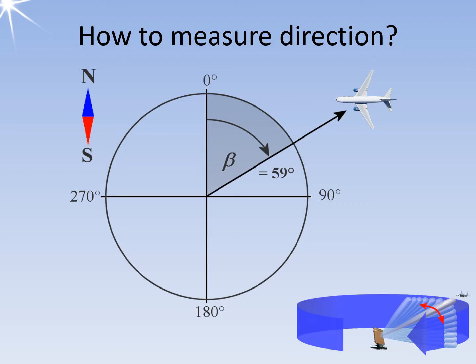Three-dimensional measuring radar sets divide the antenna pattern into narrow sections and measure the distance individually within these sections. Thus, an elevation angle is measured. The height can be calculated from the target distance and the elevation angle.